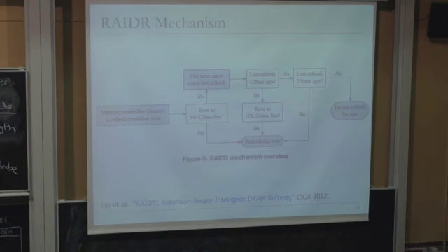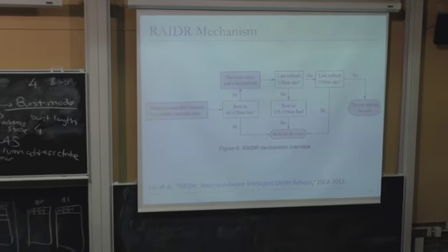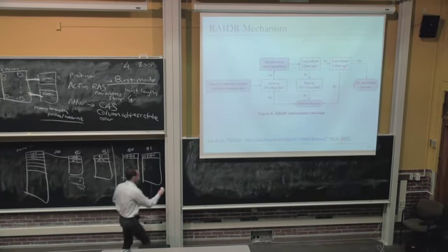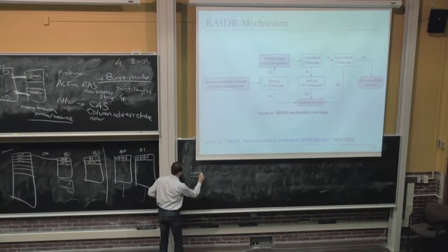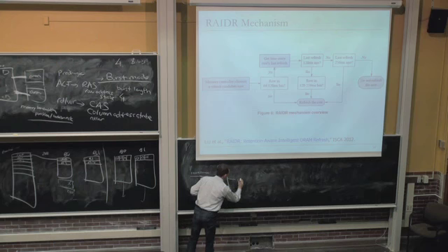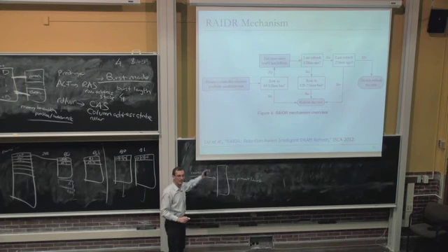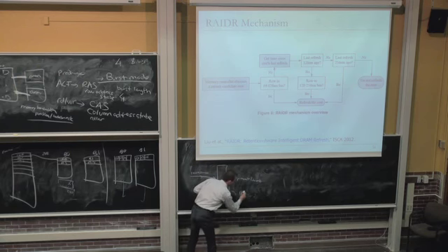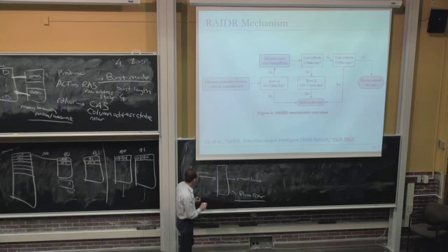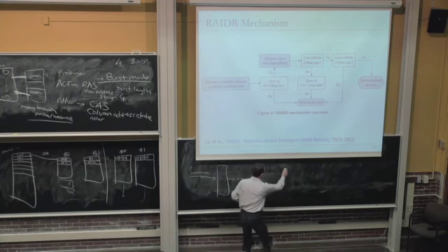Yes? What exactly do you mean by that? Is it just a storage thing which will store all the... Yes. So you can think of it as a storage. You give it the row address, and the bin tells you present or absent, which could be a content-associative memory, right? But that's expensive. So what Jamie came up with is to actually implement this with a Bloom filter. Do you guys know about Bloom filters? No? Well, the idea is very simple. It's a bit vector.